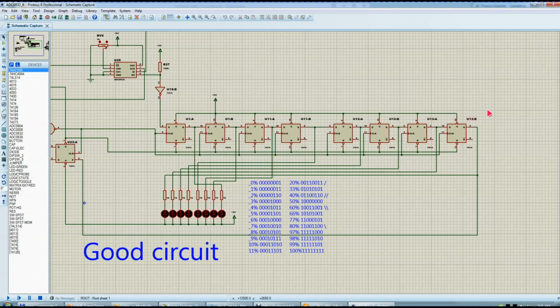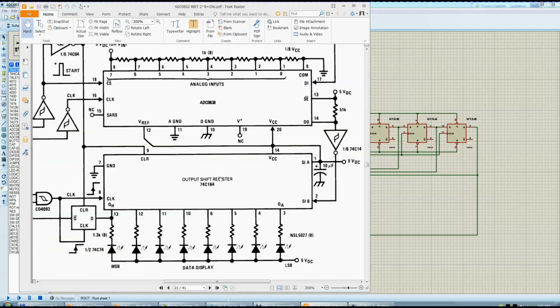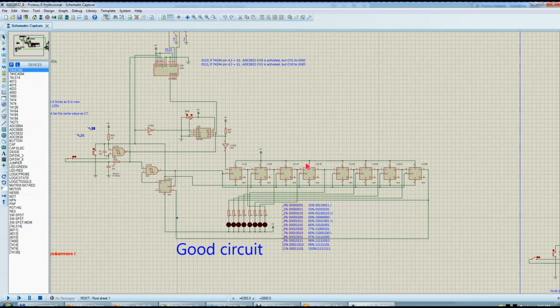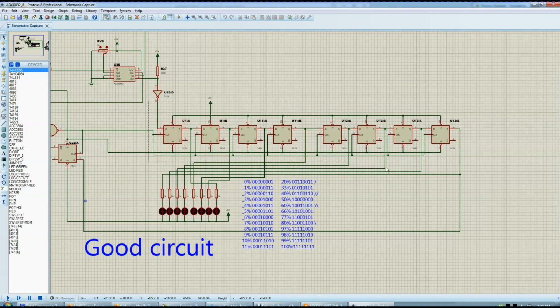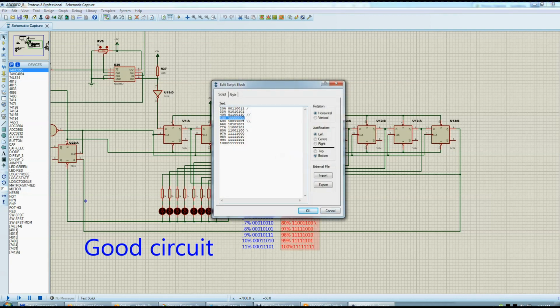Very interesting. And if you are using this configuration that I'm using here with the flip-flops, I am getting another very different configuration, slight deviations. But for some exceptional bits, I'm getting the same result whatever I'm using. If I'm using this chip, or the 2 chips that are 4-bit shift registers, or this whole entire line of flip-flops, the common values are zeros. Not really. On some chips I get all zeros without the first one as 1. But on 100% I get this, this is common, 100%, and on 50%. On 50% here I get 1 and the rest are 0 on every chip.